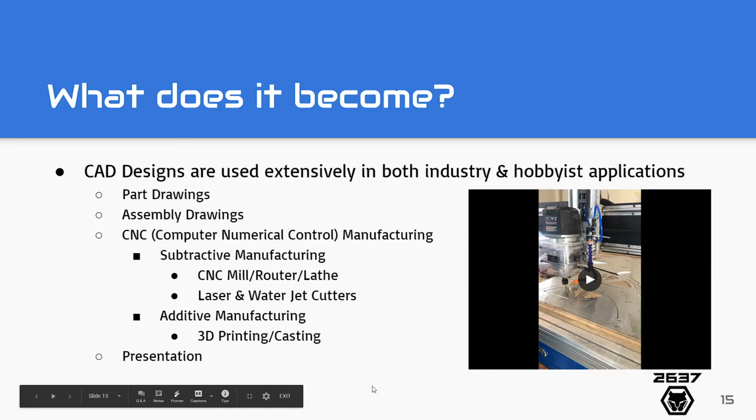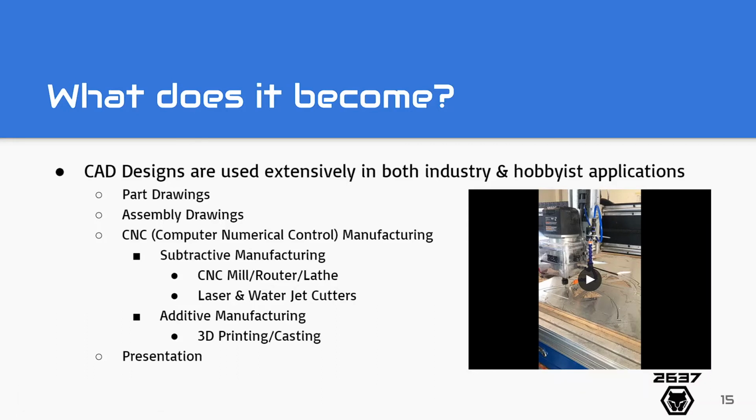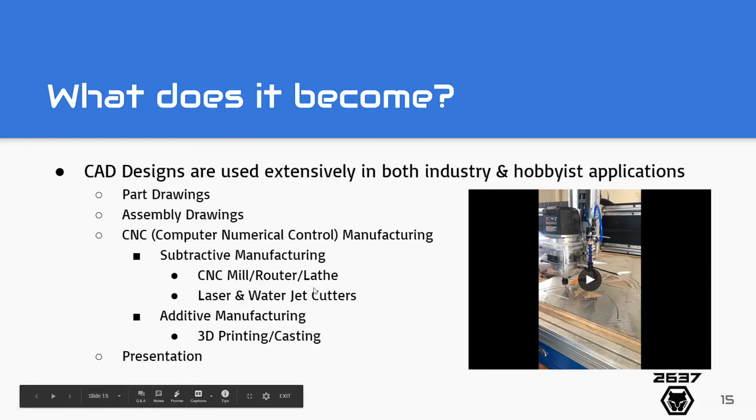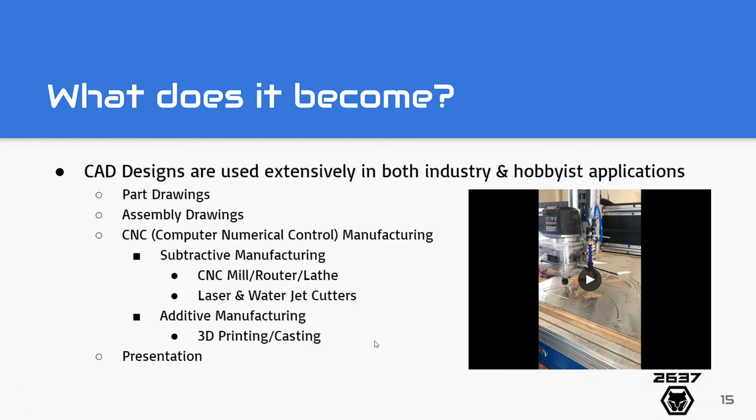And one thing I just wanted to add on, so a CNC mill and a lathe, there are versions of mills and lathes that are just CNC. So there are mills and lathes that you operate by hand, but with these, a computer is more accurate. And this machine, it looks very expensive. It is very expensive. It looks very advanced. It is very advanced. But even this machine has tolerances up to 3 thou, so 0.003 of an inch. And you're going to have to design your parts according to that.